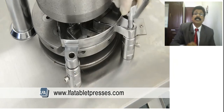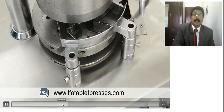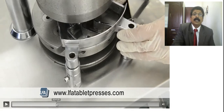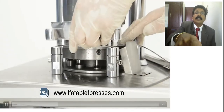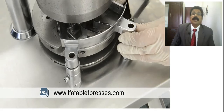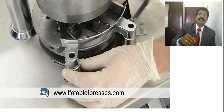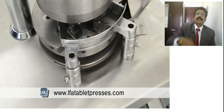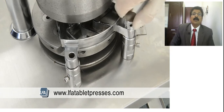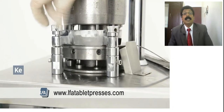Can you see the feed frame? See once more, I just missed showing you. I'm just going back to show you. See, this is the feed frame, and he is keeping it over that thin blade and then fixing it over that screw and bolt. He is just making the bolt clear, and you have to tighten the bolt properly,